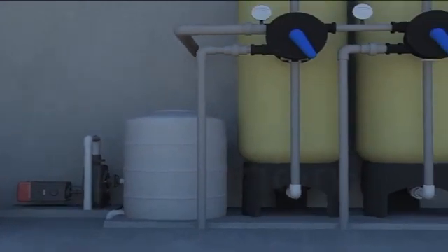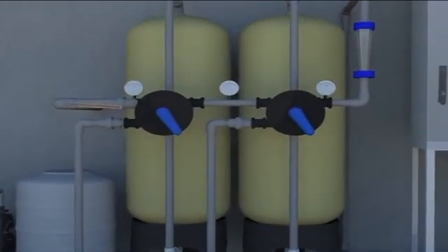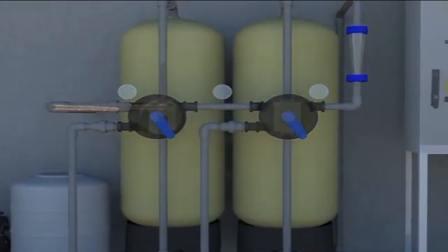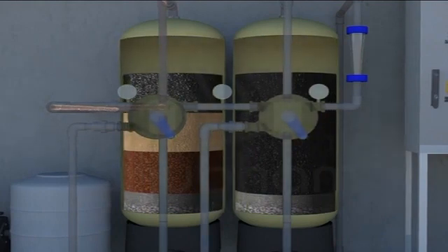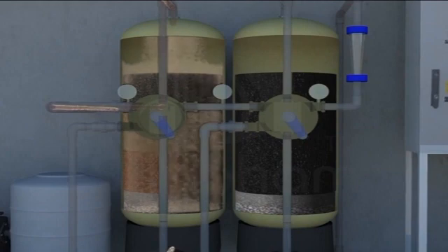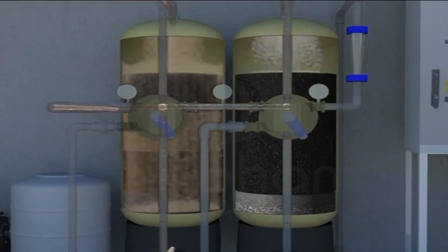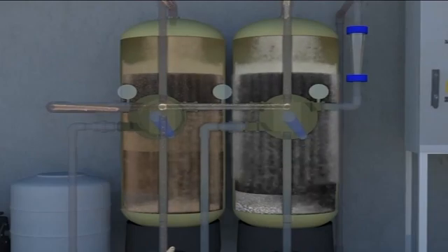After the biological step, treated water can be further polished by means of specific tertiary treatments such as the use of membranes, for example microfiltration, ultrafiltration and reverse osmosis, or other chemical physical processes such as activated carbon, precipitation, chelation for the removal of specific pollutants and to further improve water characteristics.